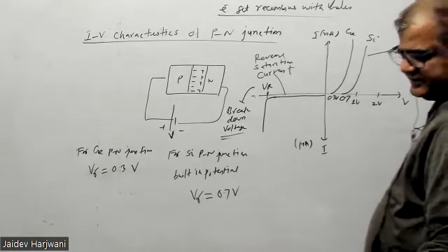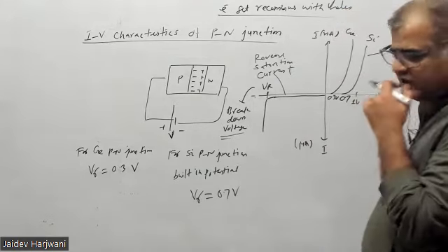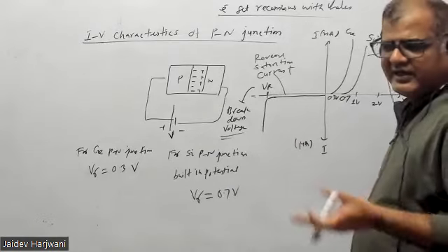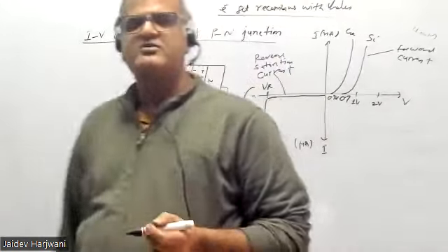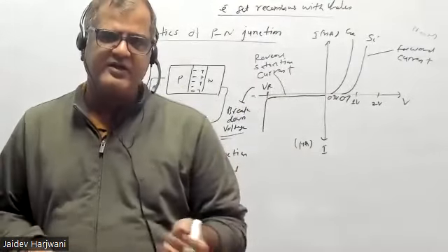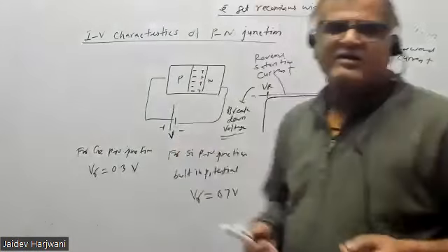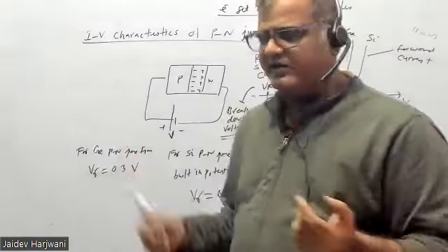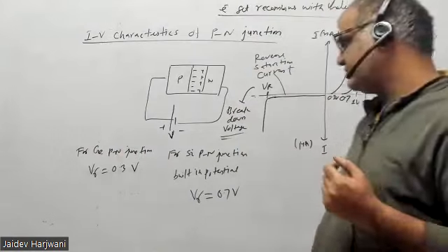But whenever a reverse bias is applied on the PN junction or diode, a microampere current will flow. I can take this current as 0. So I will say whenever the diode is reverse biased, it does not flow any current, because a microampere current means no current actually. So the junction can behave like an open circuit. The diode will behave like an open circuit and will not allow any current. For practical circuit calculations, you can assume this.